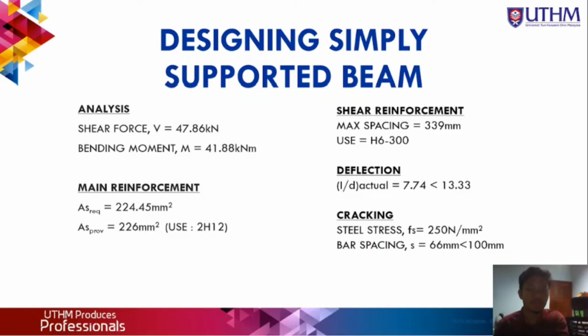For main reinforcement, I use 2H12 for the reinforcement beam, and for beam link spacing is H6-300.